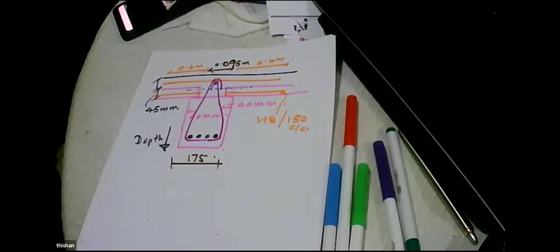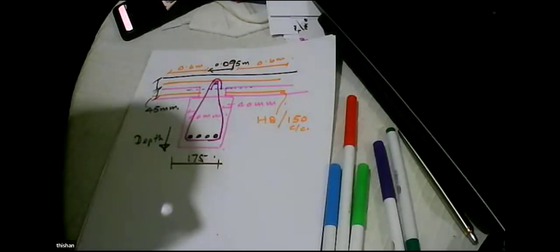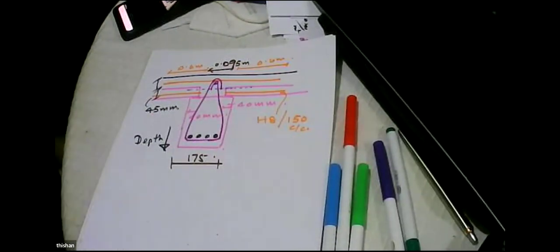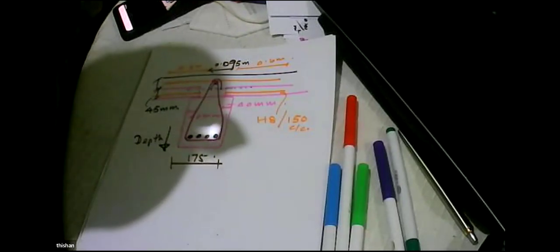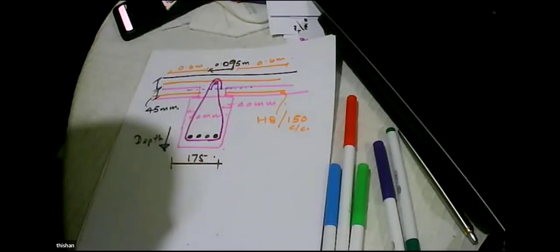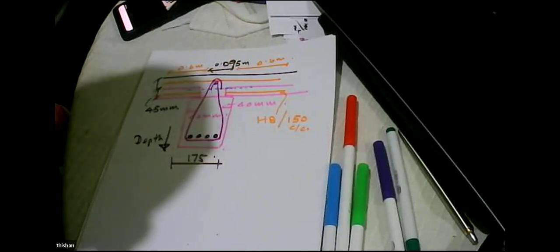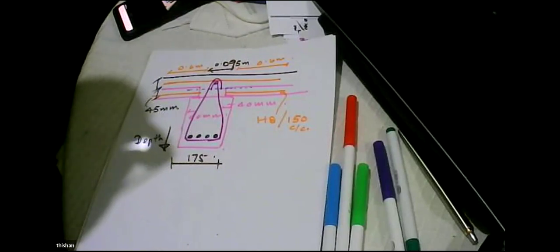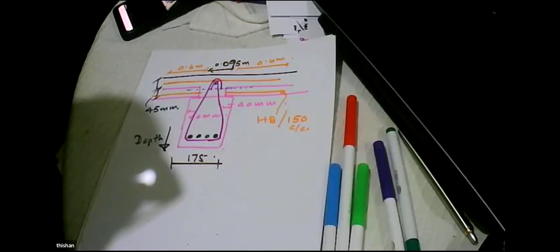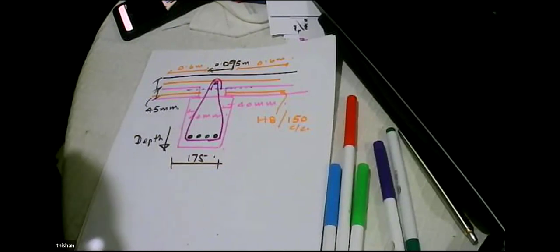So very significant cost savings can be made versus the traditional systems. And even for a 6 meter span, what becomes larger is the beam, but not the slab. Slab will remain the same 90 millimeter thickness and continuous over every 2 meter, where there will be either a wall or a beam.